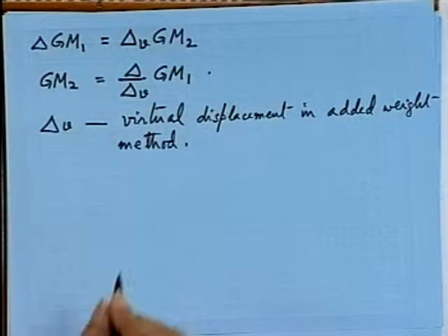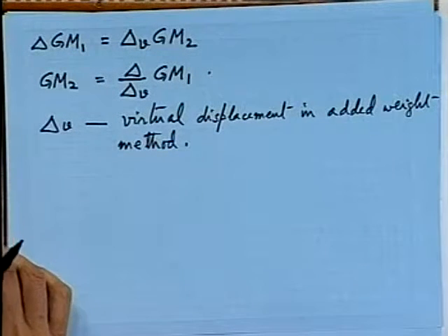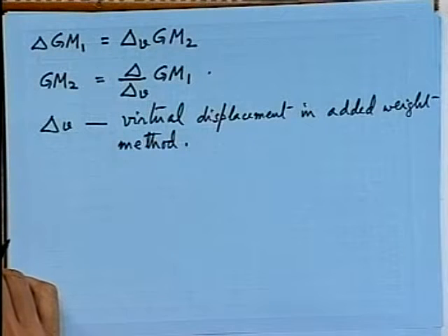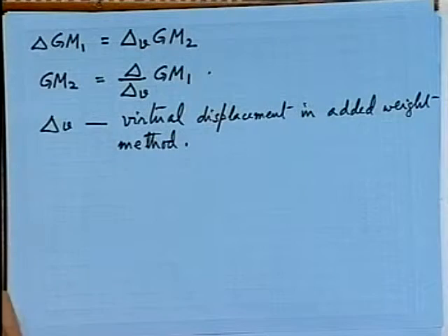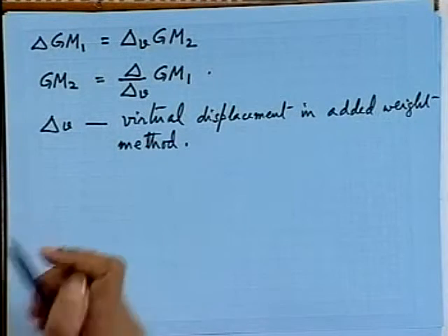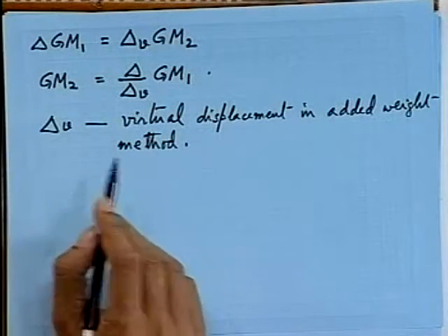So one should remember that the righting moment is to be the same in both types of calculation, lost buoyancy and added weight, although the GM calculation is going to be different. So one should not stop the calculation after calculating GM, in either lost buoyancy or added weight. If one wants to go through the whole calculation, it is always better to multiply it by the relevant displacement and get the righting moment.